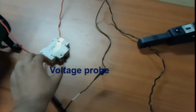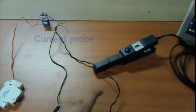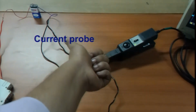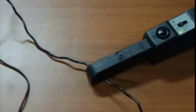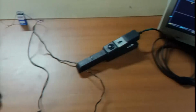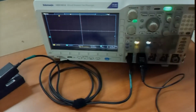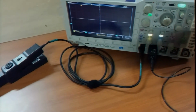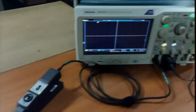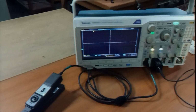So there is a voltage probe and a switch which we will switch on, and we will observe the waveform using a current probe, and what we will do is, of course, find out V and I and plot it. We may of course scale the voltage and current so that they are visible on the same scale on the oscilloscope.